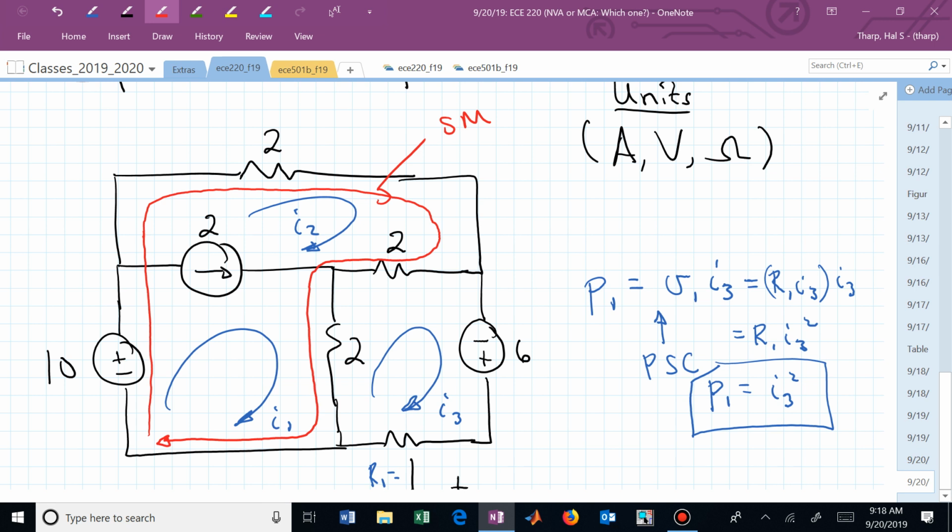Is that okay? And it is. KVL works around any closed path that we identify in the circuit. And that's good because we do it also with air gaps, don't we? If we had a resistor hanging off here, we could find a KVL maybe around a certain path and then find what that voltage dropped across the air gap might be.